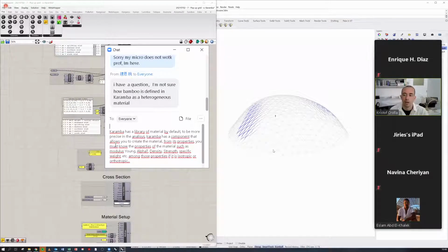But from an argument's perspective, why we didn't go down that avenue is that the structure becomes stronger if the fabric operates as a load carrying and load distributing element in the structure. So by not having it do that, the structure is again a little bit weaker than what it would be in reality. So it's safer not to calculate it than by incorporating it. It's a safety factor that you're embedding in the setup. But you're correct that in principle it would help.